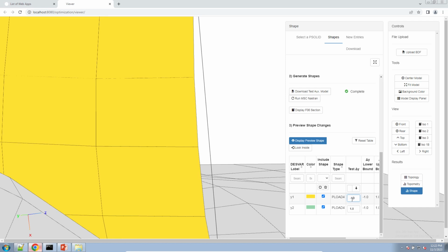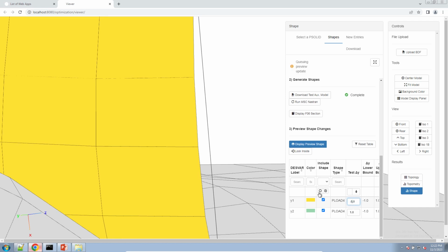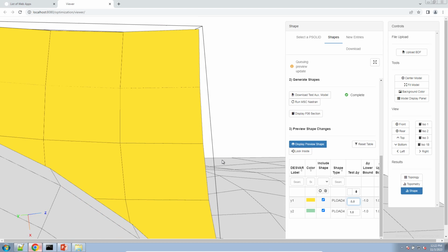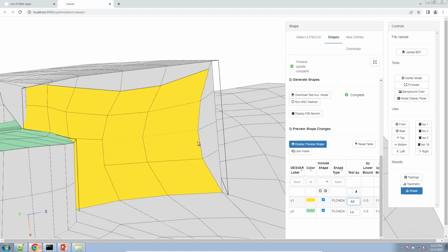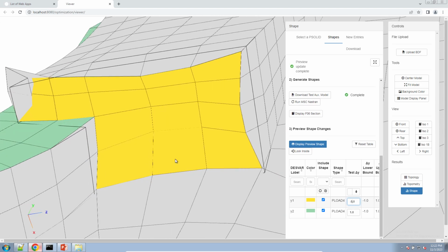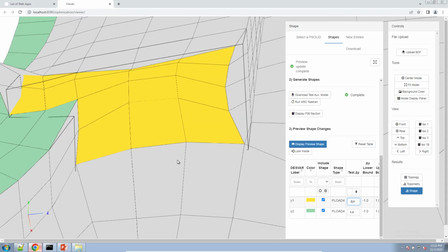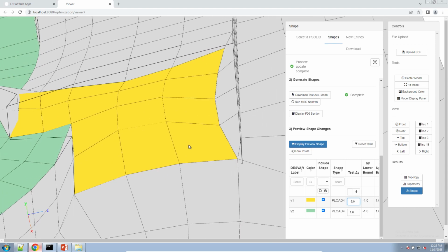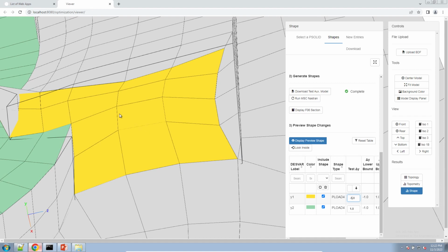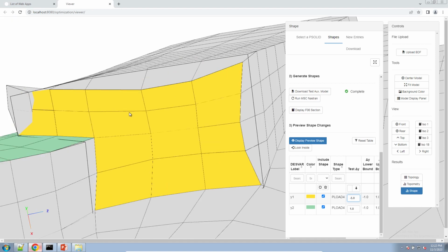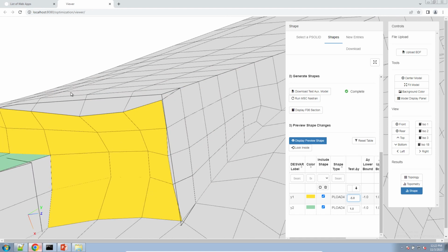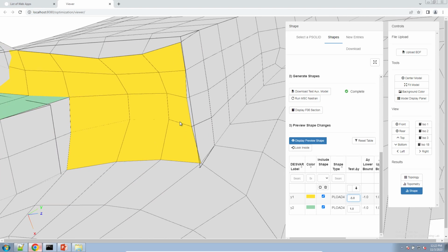Now, let's do this a little bit more. Let's increase the change by an increment of 5. What would that look like? Now, you already see what the problem is when I expand or contract only on this set of element faces. We have the issue where the adjacent elements are not expanding or contracting with these primary faces. So we should introduce stretching in those adjacent element faces.